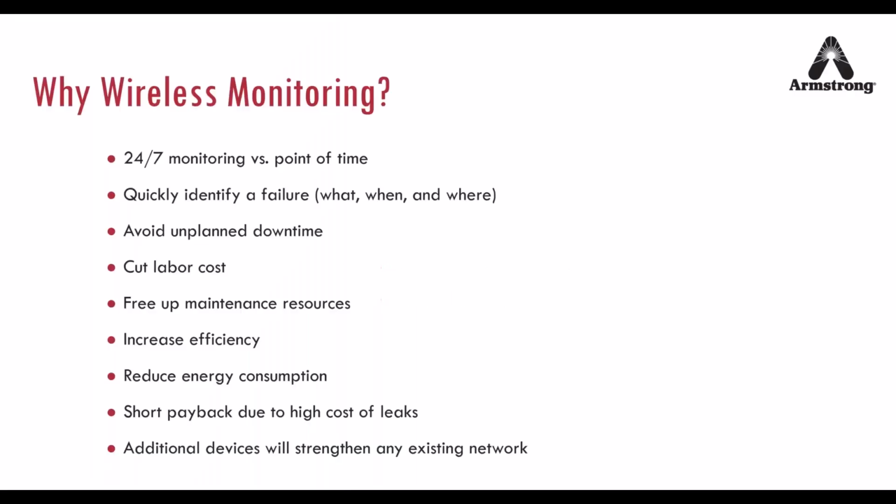So, first, the main question is, why wireless monitoring and why monitoring? On steam traps and safety relief valves, for example, you typically check them once or twice a year. That means you could check it and it's okay, and then it's failing the next day. In the case of a steam trap, it might be blowing steam for the rest of the year, or a safety relief valve might discharge fugitive emissions to the atmosphere right away. It could go to a flare, and you have a big flame on the flare, and you're wondering which of the 100 valves that you have is open.